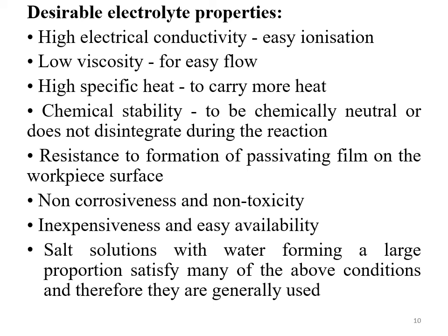It should not cause any kind of corrosion on the workpiece. And it should be non-toxic. That is, the fumes, smell or odor of this electrolyte should not be harmful to the operator, because he is very close during the machining. And it should be inexpensive, as a lot of electrolyte is required during the machining.